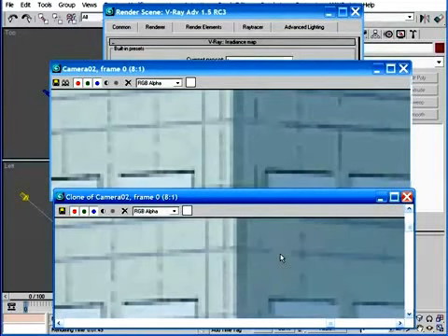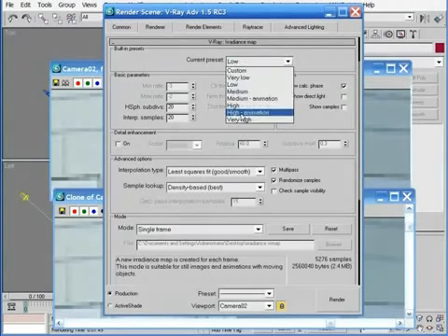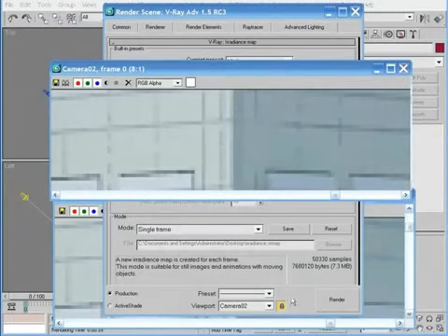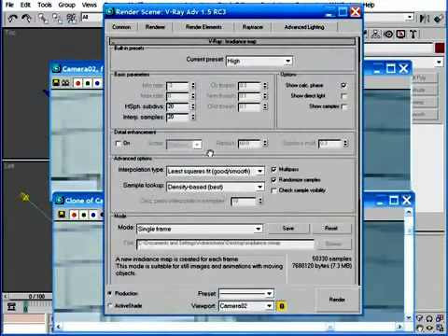Now I'm going to turn the detail enhancement off and change the irradiance map preset to high and render the scene again. And when I do, you'll notice that there is still no noticeable improvement in the detail of the reveal lines. And you could use some of the settings within the detail enhancement section to improve the effects, but the default settings are really sufficient for most situations, and improving them here just won't be worth the cost of the increased rendering times. This demonstration does not mean that detail enhancement is not a worthwhile setting. It's just that its effects are negated by some other problem, some other setting in VRay, and we need to find out what that is if we want to bring out this detail.